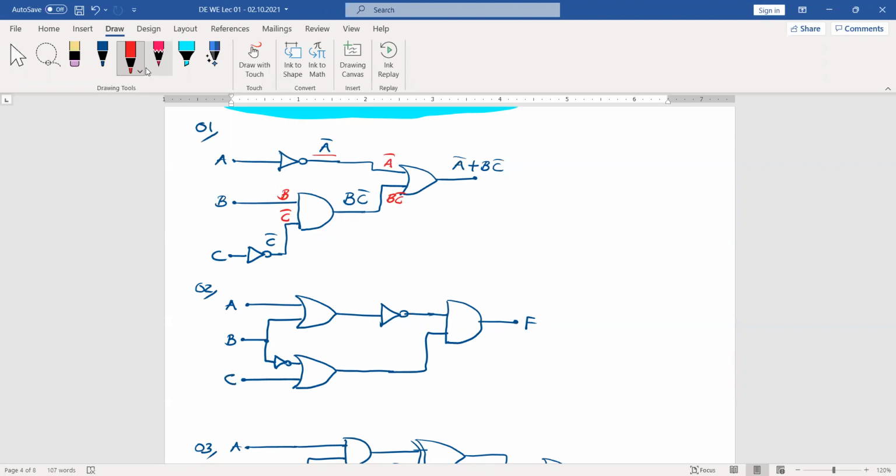Okay, here, this is A and this is B. Because of that, this is A plus B. And the function of this one is that whatever input is coming in should be inverted. Then this is A plus B bar. And when you consider this gate, this is B. Because of that, here we have B bar.